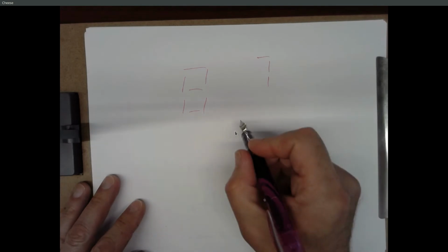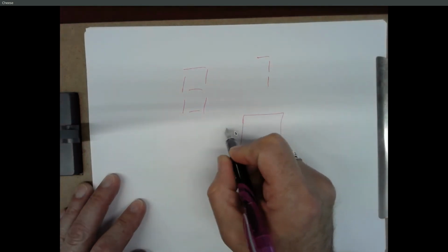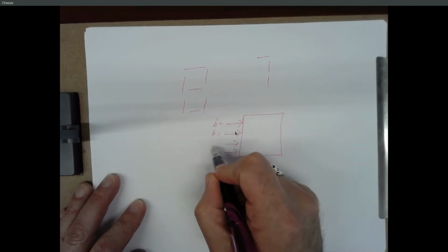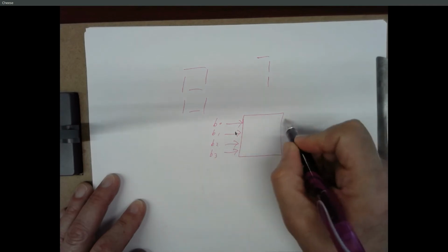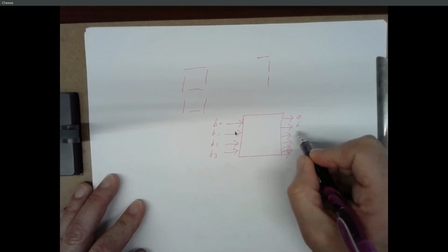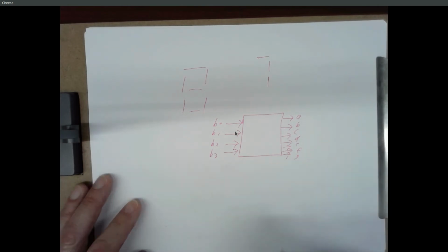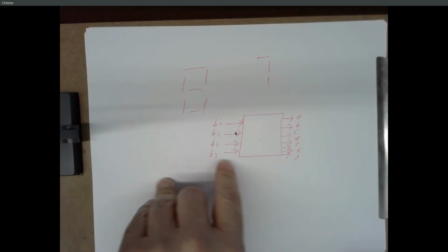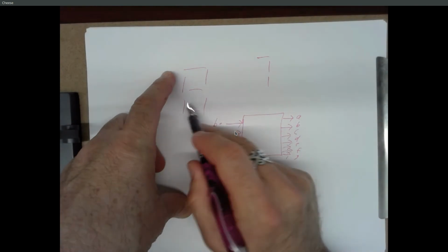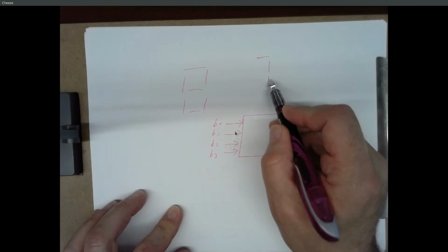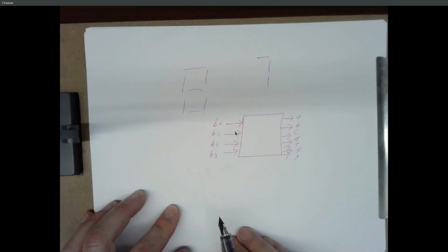And so what we would like is some kind of box that takes in a 4-bit number and drives each of these 7 segments, so that if I put in the binary equivalent of 7 and I have these 7 outputs connected to my 7 segments of my LED display, it will send a 1 out on the pins that light up those 3 LEDs, and it'll look like a 7.